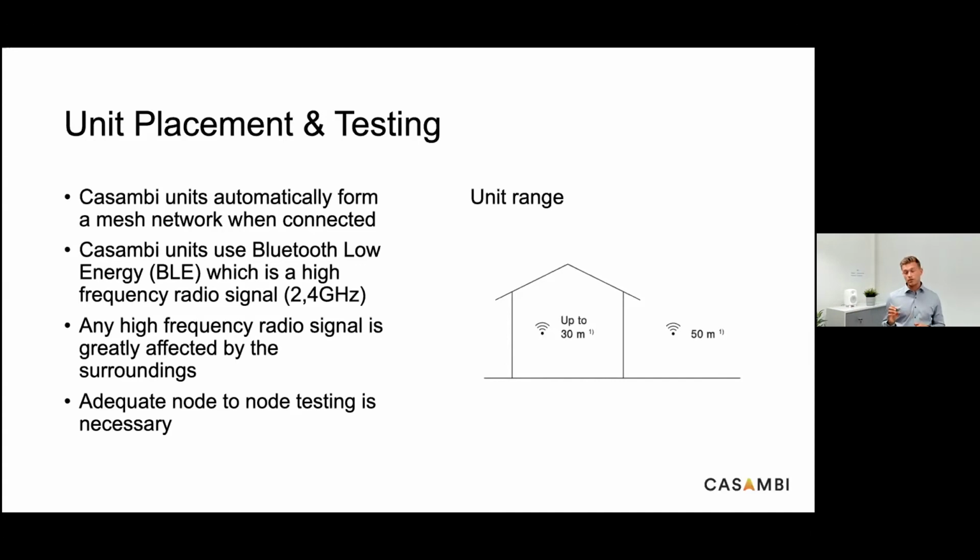And with this, it's also good to remember, on our website, we have plenty of materials that you can look at, plenty of documentation on how to do this, but also typically to ensure testing luminaire to luminaire. And this is purely because if you're testing between mobile devices, for example, if you use maybe your iOS Apple device, then typically the Bluetooth signal will be a lot stronger. The connection will be a lot stronger from that phone device to your Luminaire. So it may be absolutely fine that you can actually talk to it. You can dim it as normal. But then when you take the phone out, you set up all the network, then you might get some issues in terms of the range. So we will always stress that it has to be tested from node to node, and that is Luminaire to Luminaire in this case.